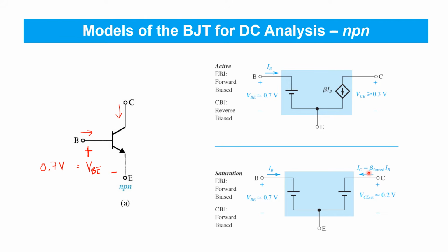It depends purely on the operating point of the circuit. So these are the two approximate models that we can use in place of the NPN transistor for the analysis of BJT circuits at DC. Finally, just a reminder that if there's no forward current flowing through the base emitter junction, then the transistor is simply cut off and there's no currents flowing.